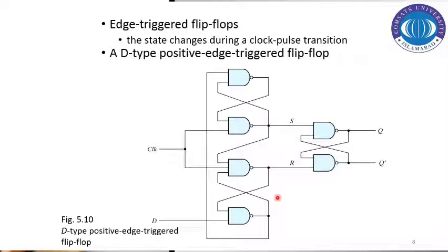Now the next important thing, the most important thing, is how we are going to generate this clock source in Verilog HDL, and there are several ways to generate the clock using Verilog HDL. So let us first see how many methods there are in order to generate the clock. Then we will move to ModelSim, and we will see the basic structure of our D flip-flop and the test bench that is used to test our D flip-flop. And in this lab session basically you will be implementing this diagram, and you will be simulating a D flip-flop in order to see how the synchronization is made and how Q and Q prime are related to D.